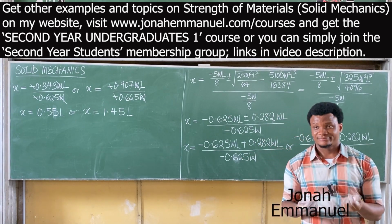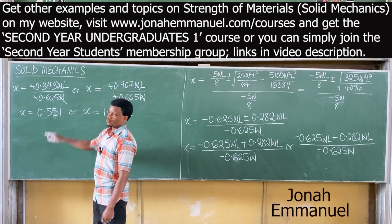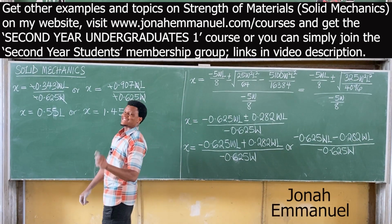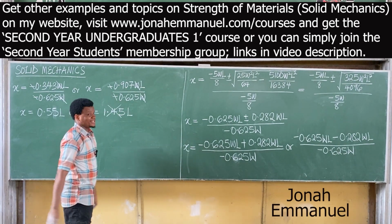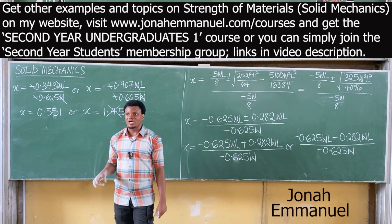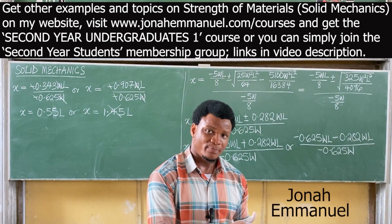This is another hard one. Now it's just flowing easily because I've already told you how it's done. From here, the value of x is always the one that has 0 point something, not 1 point something, not 2 point something, because this value here is bigger than the span of the beam. So x will always be equal to the one that has 0 point something and positive. In any case where you solve up to this point and you're having two 0 point something values, the differentiating factor will be that one will be positive and the other negative. So which do you take? The positive one.